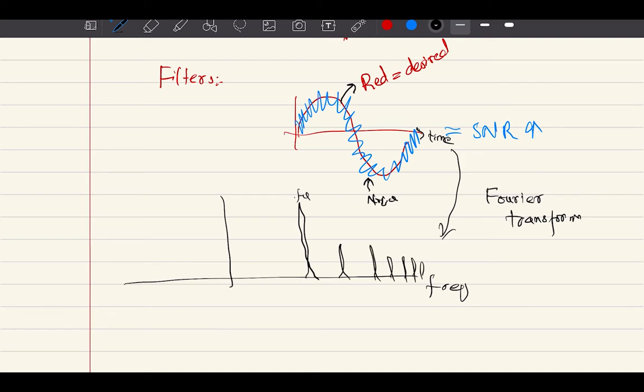If you have more noise, different replicas of the frequencies and different Doppler shifts will keep changing your frequency. Your received signal, as I told you, is not made from a single frequency, but different frequencies from different sides come, they add up, and they give you some fading, some different frequency components.